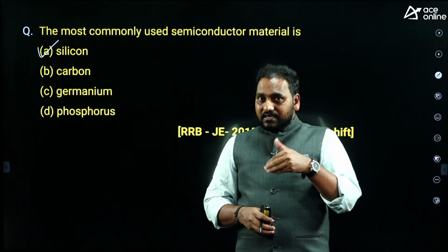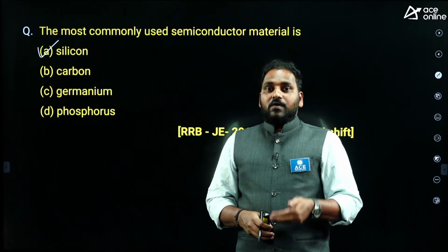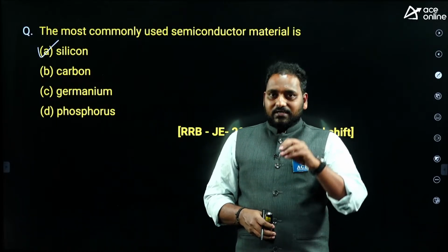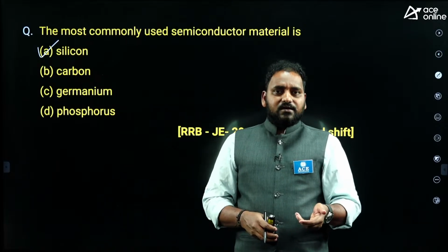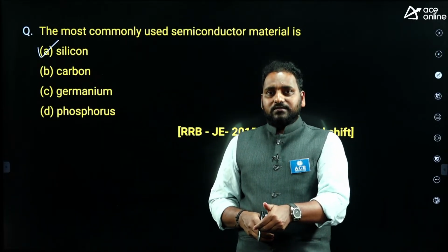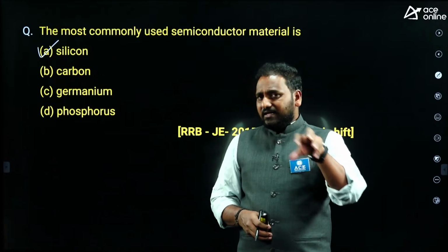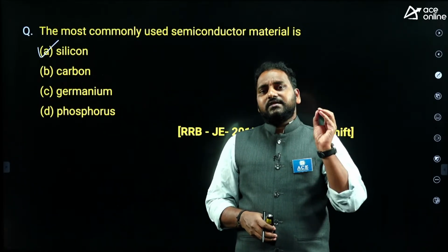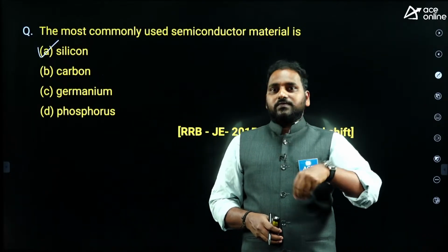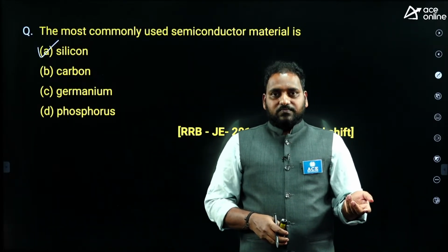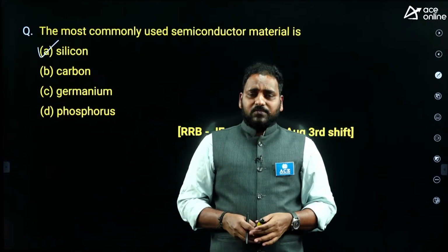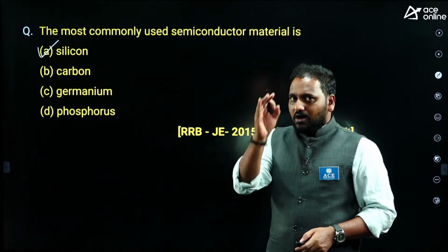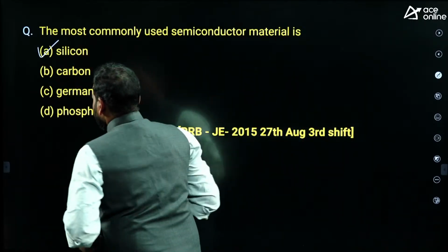That's why in power electronics also we have SCR, silicon controlled rectifier. In those high power devices, maybe IGBT or UJT, SCS, SUS, PUT, whatever may be in power electronic devices, we are using only silicon, no concept of germanium. In very rare cases, some electronic equipment uses germanium. The reason is different, because of its mobility. That's a different story. But stability wise, the best and most common element is silicon.